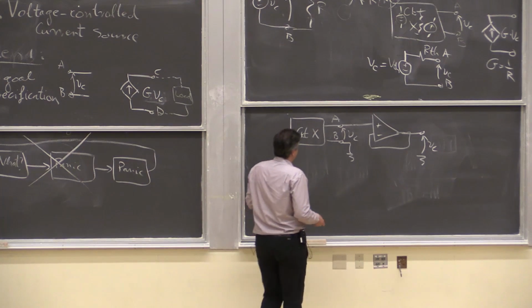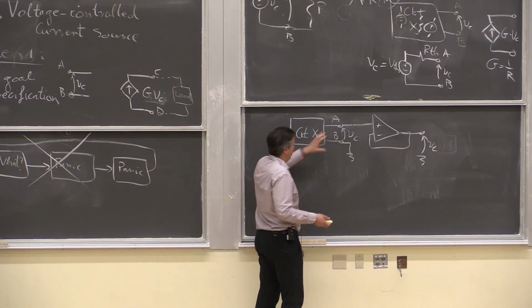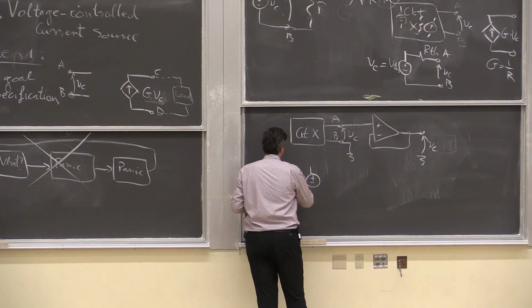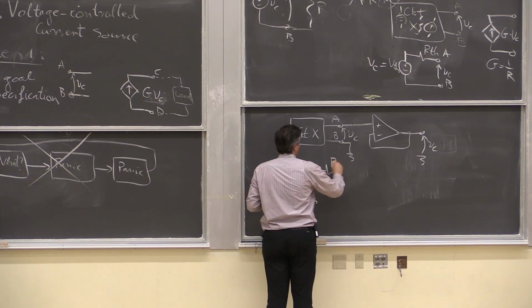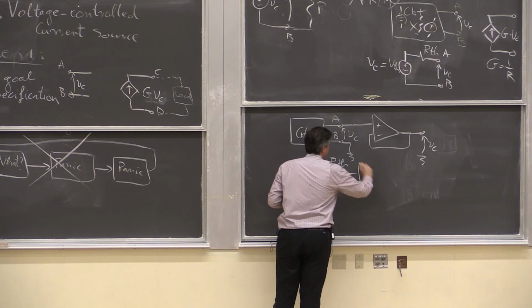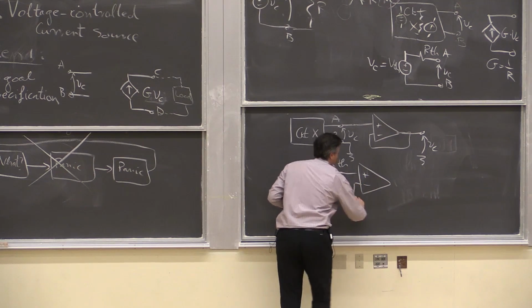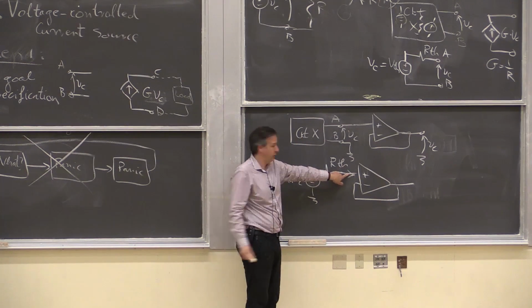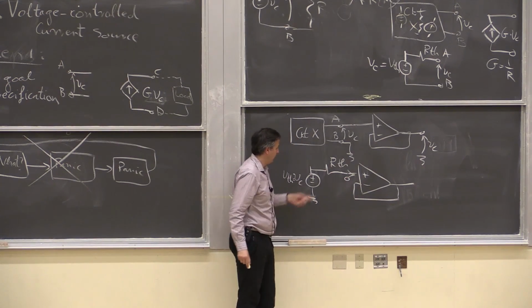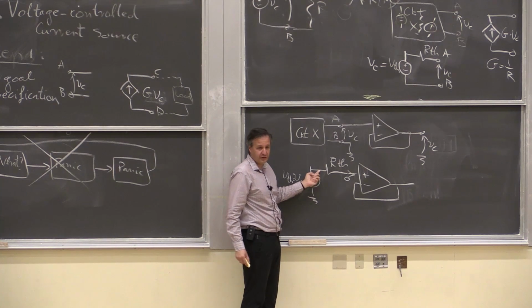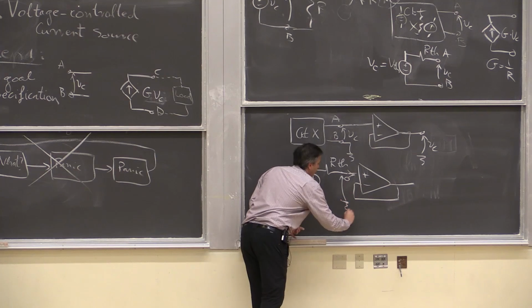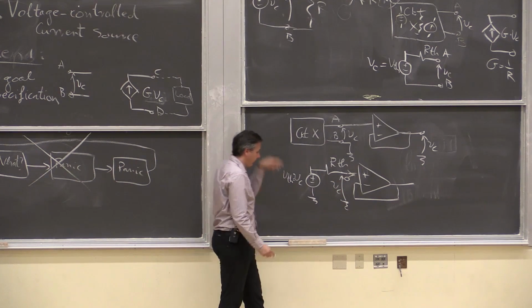In other words, if you want to see it as a model, this is our V Thevenin equals VC. R Thevenin goes into a buffer. First golden rule, this current is 0. So the voltage drop across the resistor is 0, and VC is the voltage here.